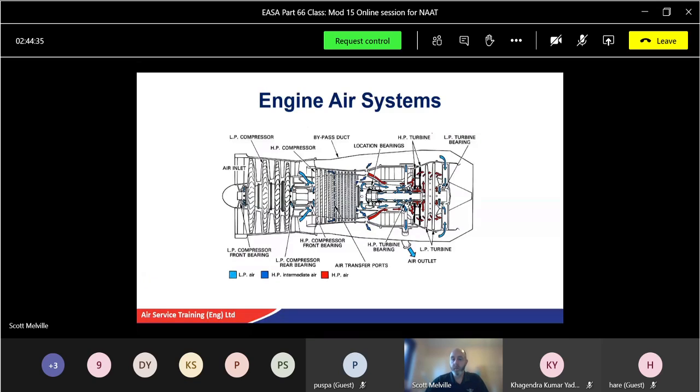Now, you can see here, this engine we've got is a twin spool. So we'll just do a quick recap while we're here. Got a nice little diagram. So LP spool, 1, 2, 3, 4 stages. And the HP spool, 1, 2, 3, 4, 5, 6, 7, 8, 9, 10, 11, 12 stages. This happens to be a Spey engine. I know that because I used to work on them. HP turbine, 2-stage, and an LP turbine, twin stage as well. And with a can annular type combustion system. So multi-can in a can, if that makes it easier to remember.